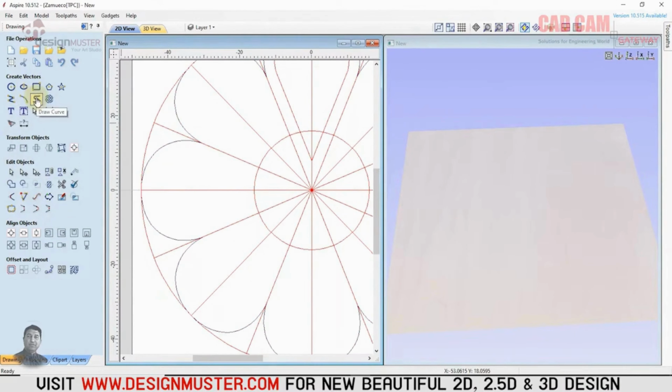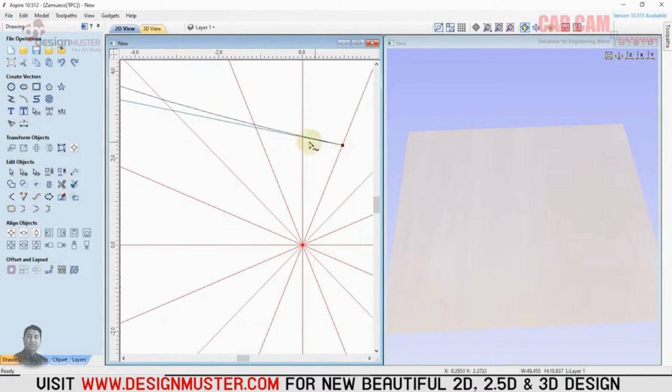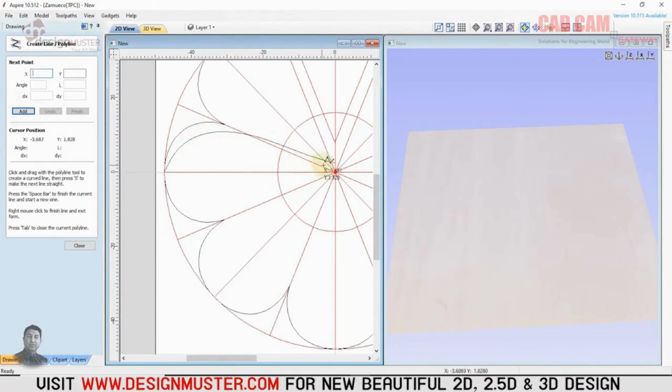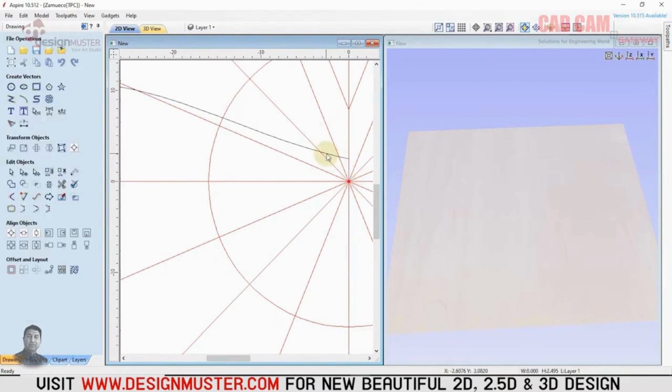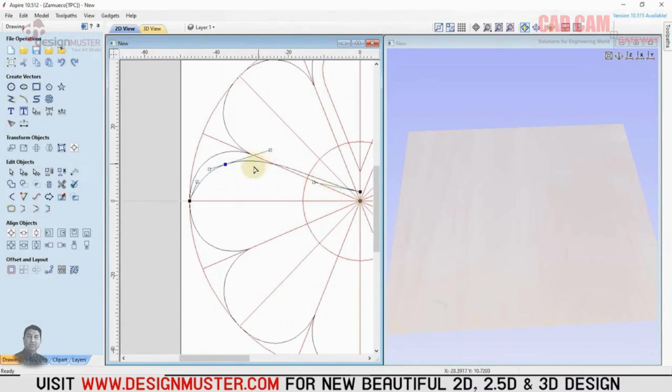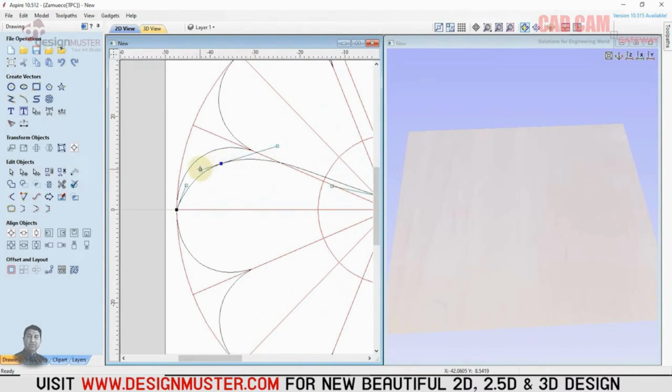Here, I selected the curve, and from this point, you can set the height as much as you want, according to your requirements. I drew this line with the node, bringing it exactly to this point. Then I brought another line down to this point. Holding Shift, right-click to join them. Now set its cross-section.